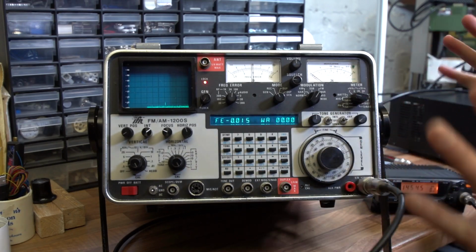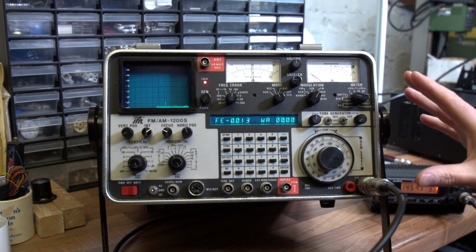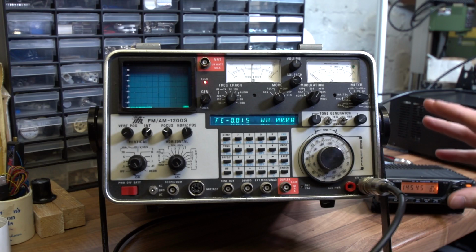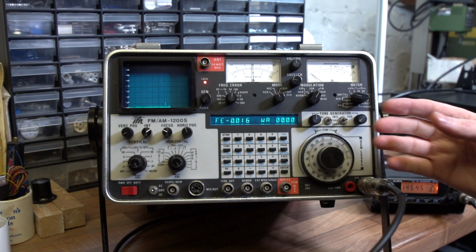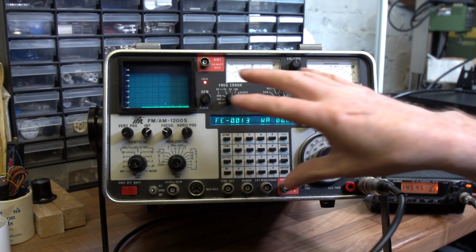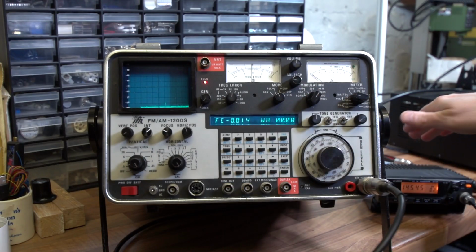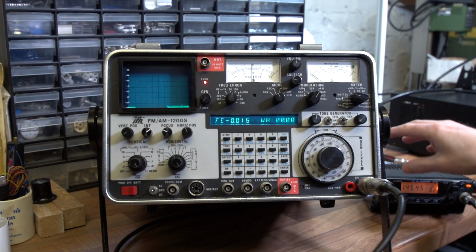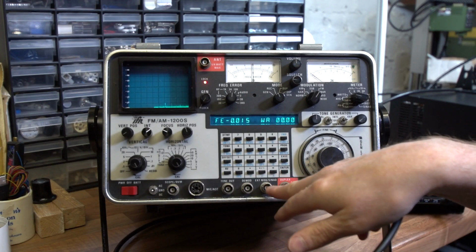All in all, it's a fantastic all-around unit for testing pretty much everything you need to test with radio equipment. It's specifically designed for aircraft radio, amateur radio, mobile radio, anything like that. It's designed to check the RF output, the modulation levels, frequency error, whether it's calibrated or not, and the other way, turning it into a generator, sending the signal into the receiver side and checking out the receiver performance.